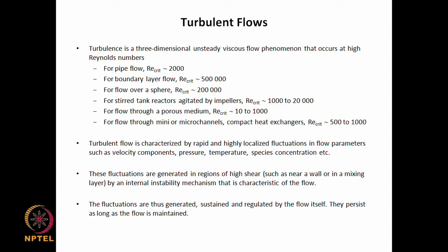And these fluctuations are therefore generated by the flow itself, and these are sustained by the flow, and although these are instabilities, they never grow beyond a certain limit, and in that sense they are regulated by the flow itself, so that instability does not lead to breakdown of the flow. Just like when we say you have an unstable bridge, then we expect those kind of images where the bridge starts oscillating very wildly and then at some point it breaks down. That kind of breakdown does not happen in this. It just exhibits very rapid fluctuations, and these fluctuations will persist as long as the flow is maintained.